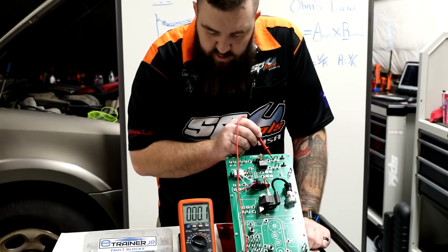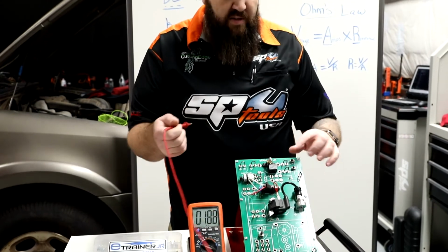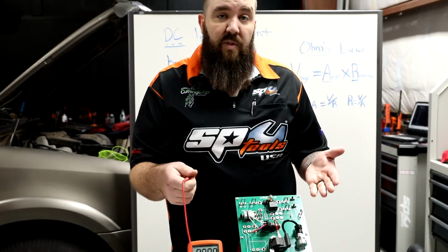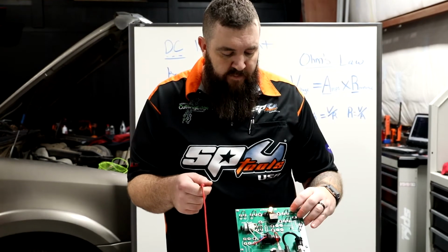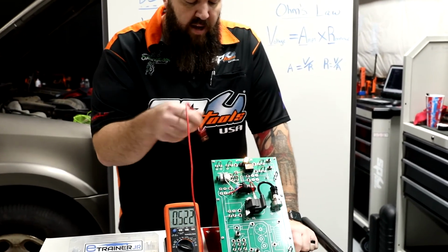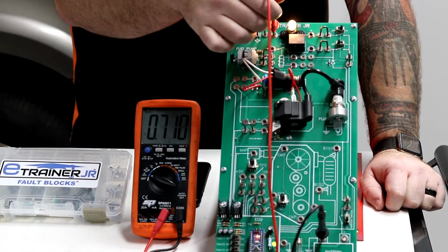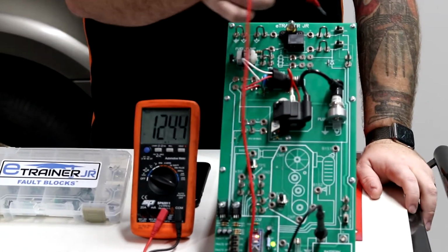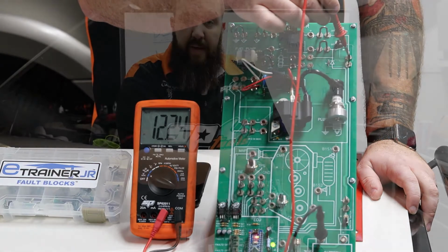After the switch, you can see we have nothing. It's because the switch is not on. Now, if for some reason that switch was on but not showing any voltage, that's how we would know that the switch is the bad part in the circuit. But now that we know it's on, we have 12 volts after the switch. And if we test right before the light bulb, we still have 12 volts. After the light bulb, if it was not lit and we still had 12 volts, then we would know that either the socket or that bulb would be bad as well.